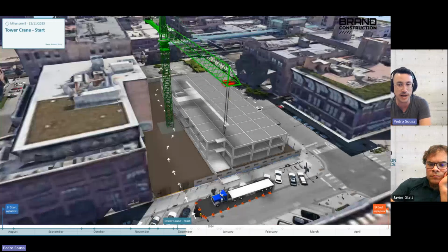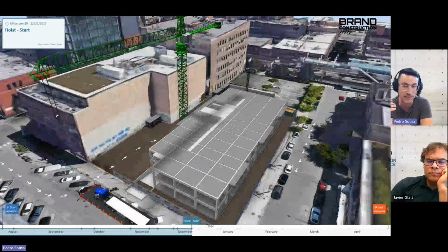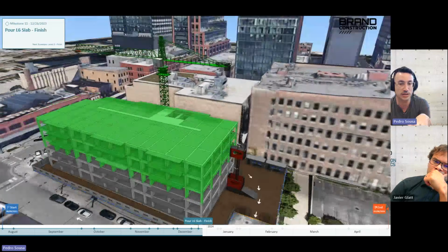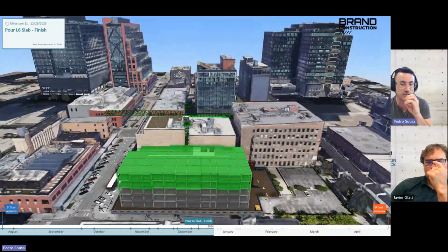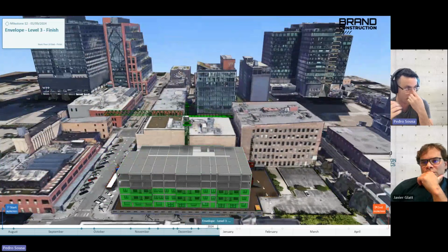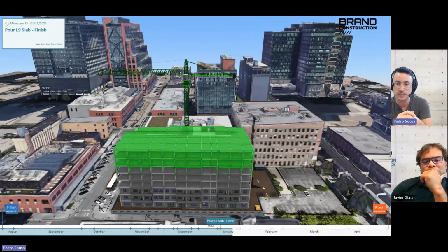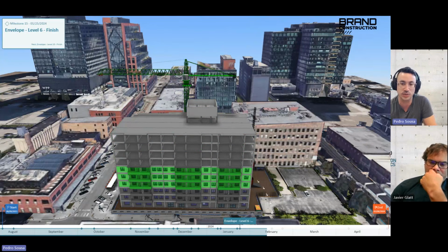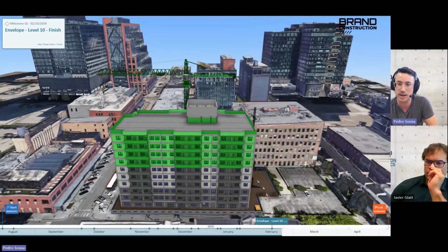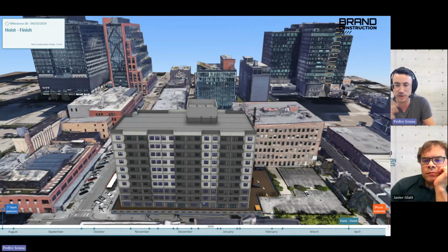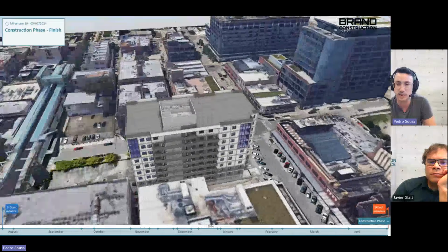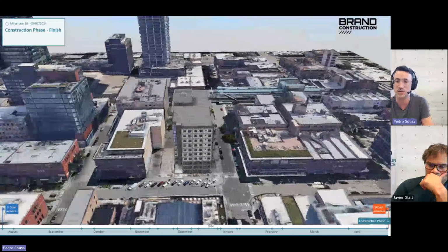You can also highlight elements that are being demolished in red, or you can use your custom colors, right? But basically, the idea is to bring the attention of the viewer to whatever is different in the model between one milestone and the next, right? So this is a good way to do that. And once I validate that this presentation is showing everything that I want, the timeline is correct, and my milestone name is over there on the top, giving the viewer the whole gist of my presentation, I can take a quick look at the last camera angles over here.